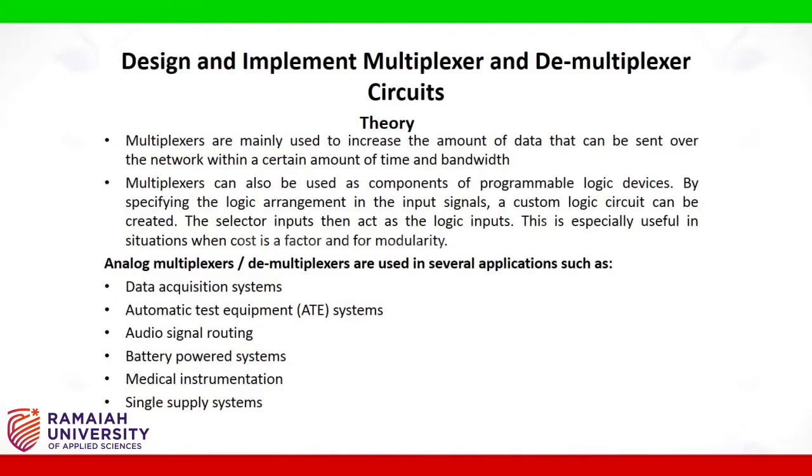Multiplexers can also be used as components of programmable logic devices. By specifying the logic arrangement in the input signals, a custom logic circuit can be created. The selector inputs then act as the logic inputs. This is especially useful in situations when cost is a factor and for modularity.